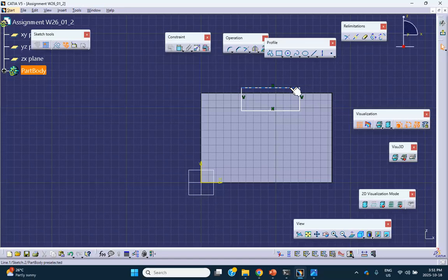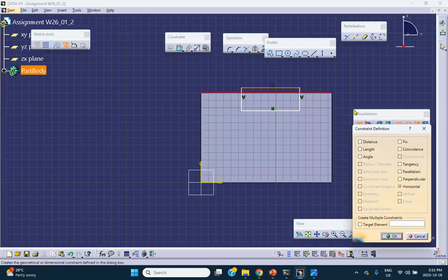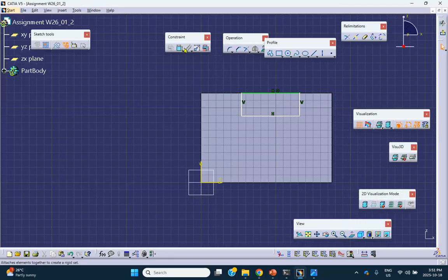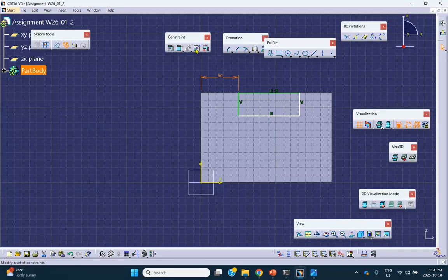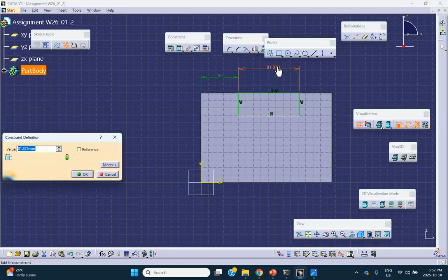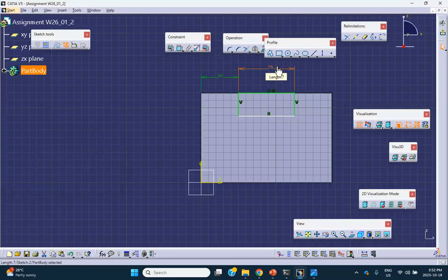Okay, first of all, I want to bring this thing down and put it there. Just control that. You make it coincident. Okay, so we want this to be 50 from here. And same thing from here to be 50, or we can make this thing 75. That'll take care of it. 75. Okay, notice that the total width is 50 plus 75 plus 50, which is 125 that I had.